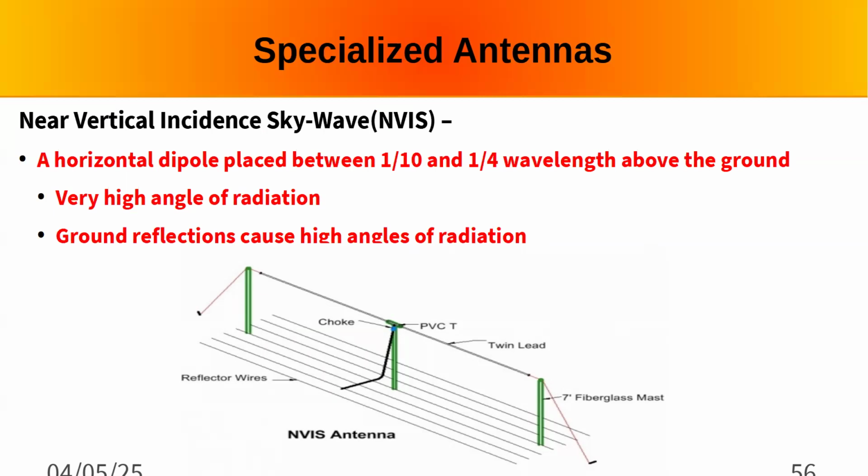If you had that same dipole that was half a wavelength high, you'd have a fairly low takeoff angle. So you're going to have a hop of maybe 1,000 miles or more. So if you want to talk to somebody in Tallahassee, it's not going to work.